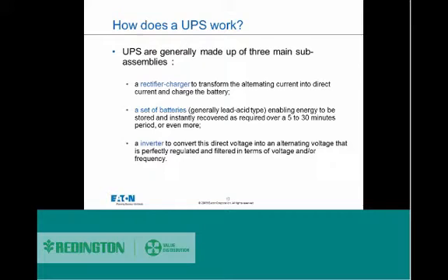Based on the level of model there will be many more components, but the three basic ones are a rectifier or charger, which is mainly used to transform your utility company's AC current and convert it into DC for the battery, which is the next component available within a UPS.